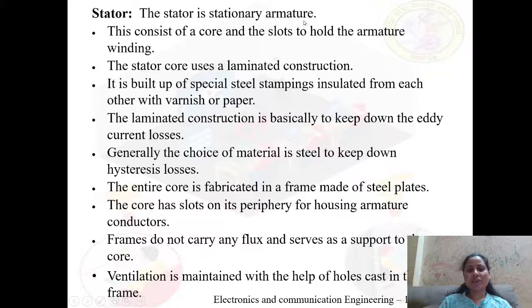The stator is a stationary armature, and it contains a core, and it also has slots in order to hold the armature winding. The stator core uses laminated construction. This laminated construction basically keeps the eddy current losses minimum. And the choice of material for the stator is steel, in order to keep the hysteresis loss minimum.